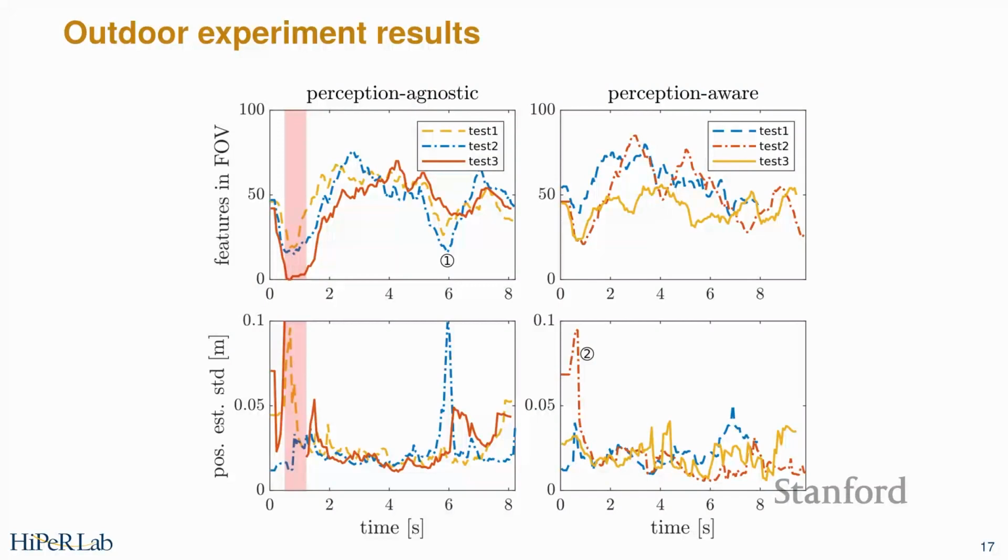What this gives us, and this is a very busy graph, which I apologize for not spending as much time on as I probably should, is that we can take these flights and show that the uncertainty of the EKF variance, so effectively the uncertainty as you're moving, is reduced. Anecdotally, we find that these fragile failures in the perception system disappear the way we've set it up. Certainly, we're conservative enough that they don't seem to be happening. I can't prove that because these are fragile, sudden failures. But with the baseline, it's fine, it's fine, it's fine. Suddenly, it's very wrong. With this perception-aware planner, we are much more robust.